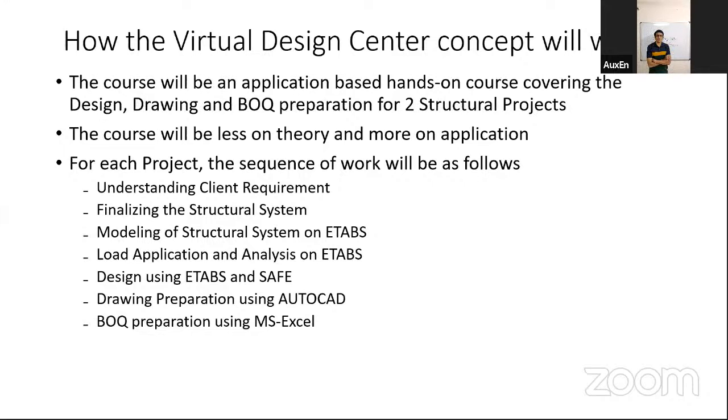So, as I told you, design of superstructure as per ETABS, substructure as per SAFE. Then once design is over, which means we have finalized the sizes and we have finalized the reinforcement, we will move to drawing preparation. We will try to prepare a complete drawing using AutoCAD.